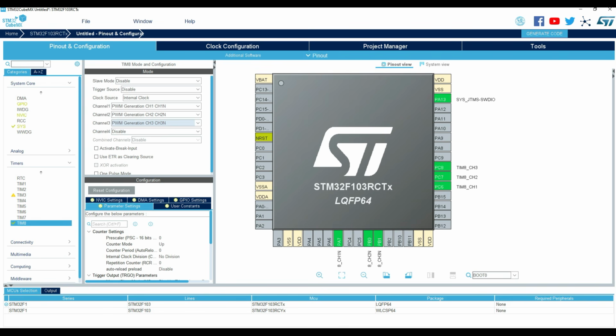These timers are not optional, they are the heart of the motor control. Without timers you cannot drive the motor at all. These are general PWM signals. A BLDC motor needs 6 PWM signals, 3 high side and 3 low side. So when I rename them, then you can see it.